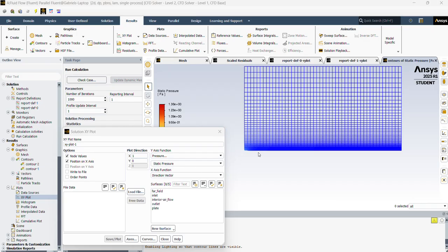Another thing you can do to find the shear stress and friction coefficient is here. You can go to your axes. You want to click wall fluxes, wall shear stress, or in this case you use wall shear stress, your X wall, because your Y wall doesn't exist, or your skin friction coefficient, depending on what you're trying to do. Again, I'm not going to go through them because I already did them. It will be your direction vector.